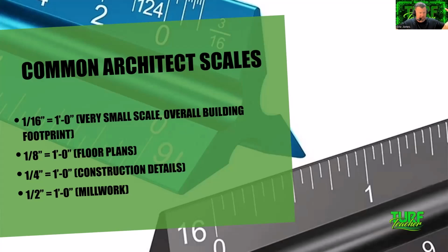but it's a huge, huge acreage property. But the 4 main in irrigation and landscape architect is 1/4 inch equals a foot, 1/8 inch equals a foot. On the engineer side, we have 1 inch equals 10 feet and 1 inch equals 20. Got it mixed up there, but it's 1 inch equals 10 and 1 inch equals 20 for engineer.